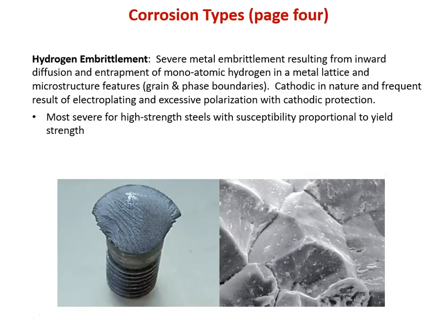And unfortunately, you can get the same situation happening when you're pumping electrons in, especially for steel. So this is the cathodic version of fracture toughness loss or environmental embrittlement. It's called hydrogen embrittlement.